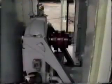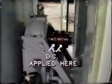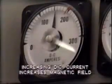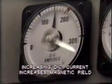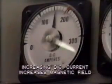In practice, instead of a rotating permanent magnet, the magnetic field is provided by an electromagnet. The rotor winding actually forms a large coil, and this is fed with DC to create the north and south poles. The DC field current is known as excitation. Increasing the value of DC current increases the strength of the magnetic field up to certain limits, and vice versa.